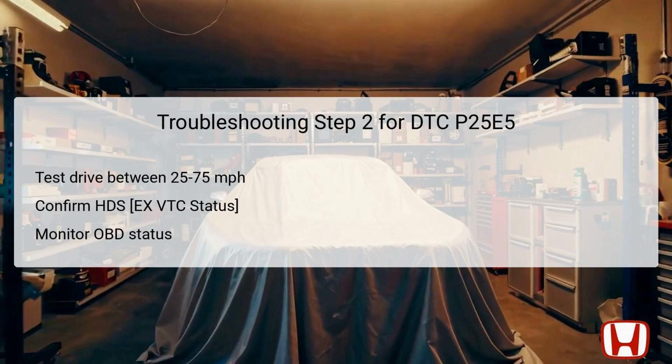Proceed to Step 2, which involves a test drive of the vehicle. The goal here is to drive at a steady speed between 25 and 75 miles per hour for approximately 10 minutes. This action simulates normal driving conditions and allows the VTC system to operate under stress. After the drive, confirm that the HDS displays an EX-VTC status indicating that it is on. This will show the system is functioning within the designated parameters.